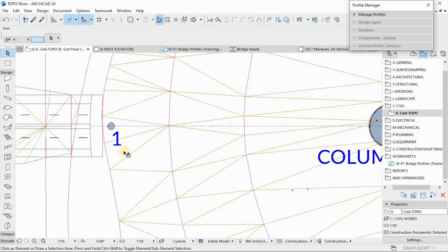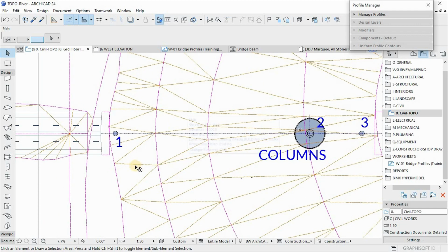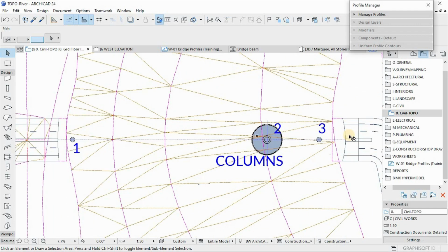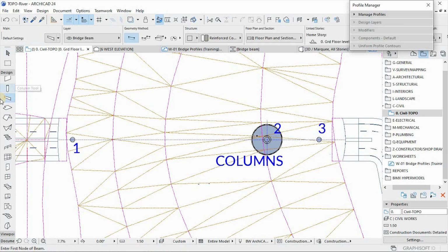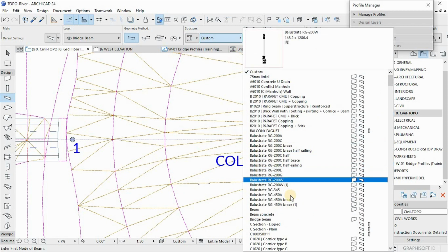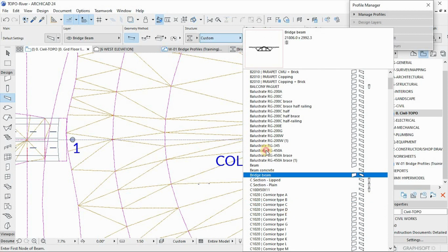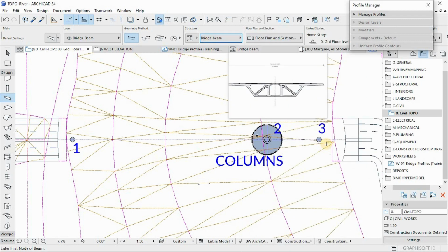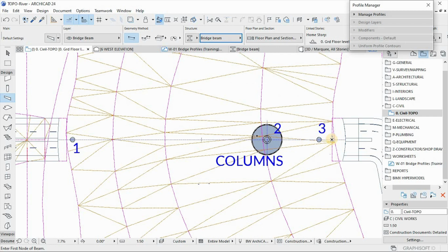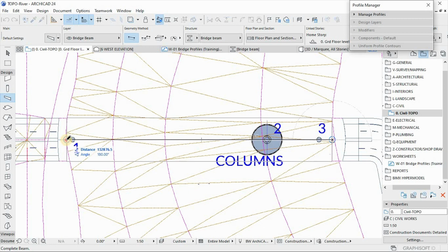Oh, sorry. Minimize that, I meant to say. And then I'm going to draw to place my beam using the beam tool. So go to design tool and activate the beam. Make sure the structure is a complex profile structure, and then go ahead and activate or define the newly created profile. So what I'll do, I'll just draw by specifying the first point and then place it at the second point like that. There we go.